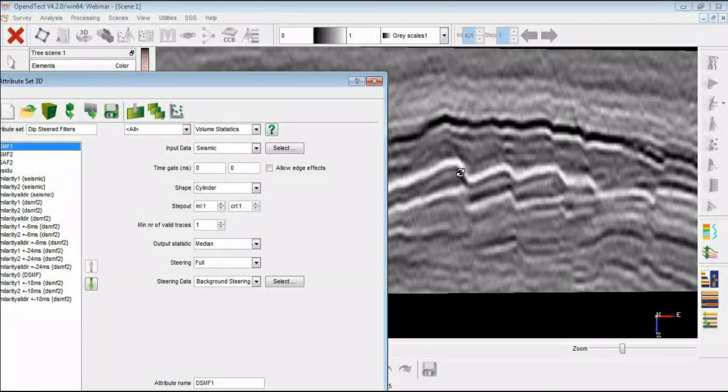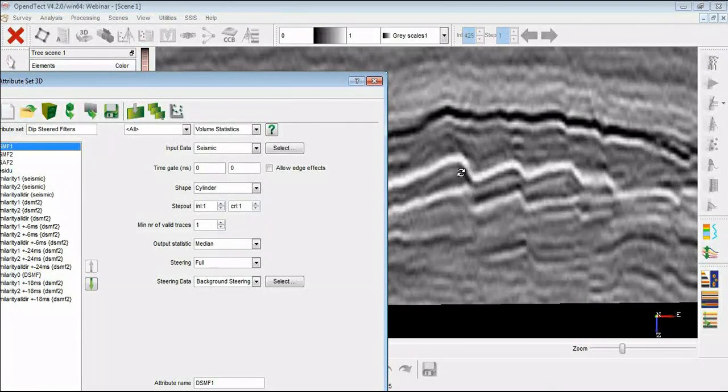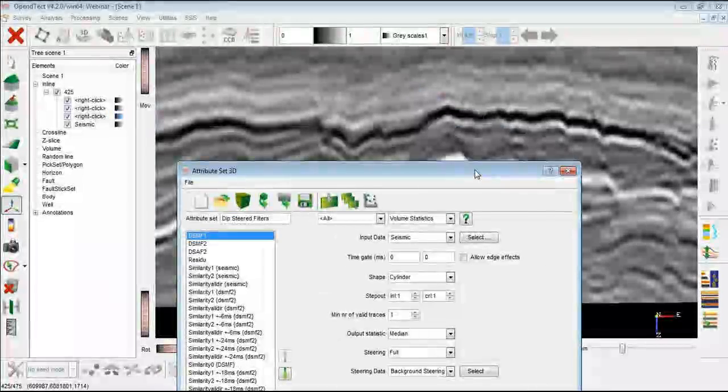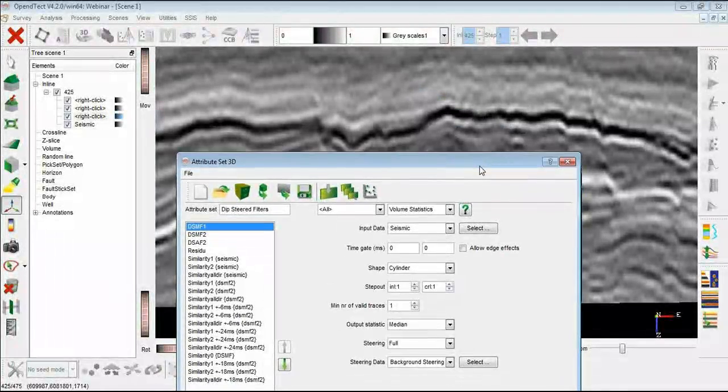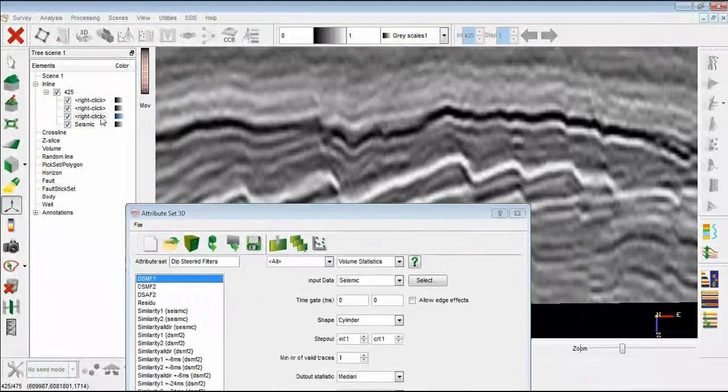That means if there's a singular spike, it will remove it. But if there's a step change, like with a fault, it will keep the step intact, contrary to an average filter. That's for fault detection. You should always use a median filter, not averaging filters, and I actually will show the difference there.